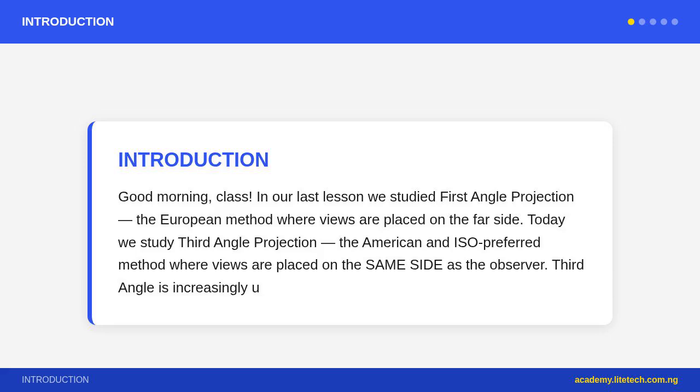Arrangement of views on the drawing sheet of third angle. Front view, center of the sheet, same as first angle, the main reference view. Plan, top view above the front view, because you look from above, the view is placed above. Left side view, to the left of the front view, looking from left, view placed on left. Right side view, to the right of the front view, looking from right, view placed on right.